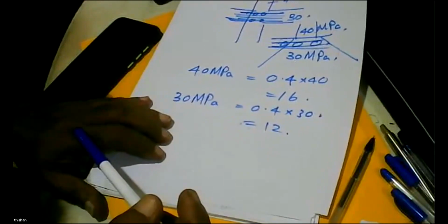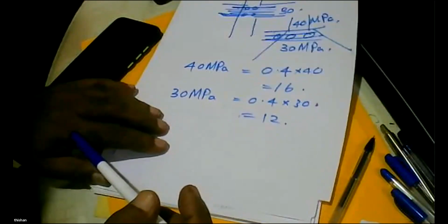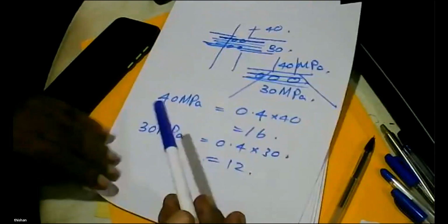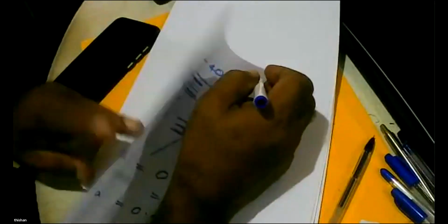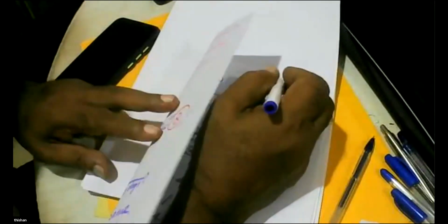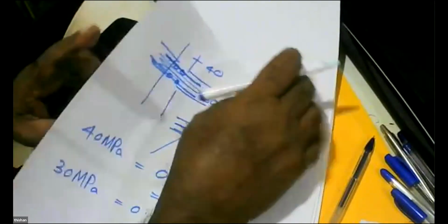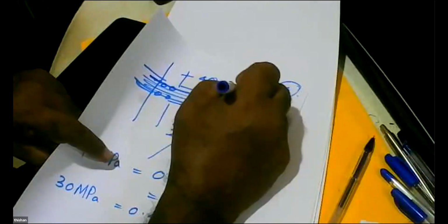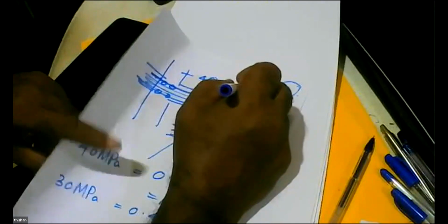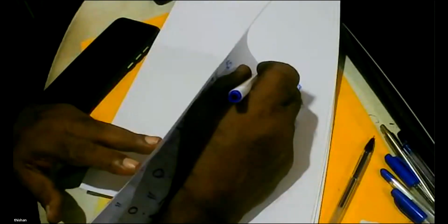I have another few small questions. As you said, the maximum of 25% of fly ash can be used. Do we have to add any alkaline activator solution if we use 25%? No. Up to 25% fly ash, you are free to do anything, provided the fly ash is type F and the carbon impurities are low.